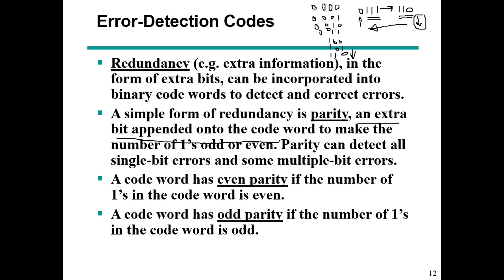Okay? I hope this helps you recall a certain gate that we studied, the exclusive OR gate. Okay? So what is the exclusive OR gate? The exclusive OR gate is a gate which will give you a 1 in the output when the number of ones in the input is odd... Okay? And a 0 when the number of ones is even. So the exclusive OR gate and exclusive NOR gate, you remember those are important gates. Okay? So here you can use those gates for error detection.